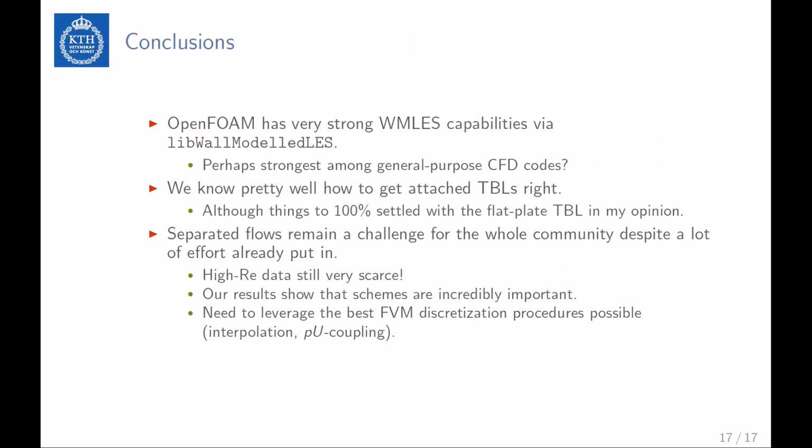So the conclusions are that we have very strong capabilities for wall modeling in OpenFOAM, perhaps the strongest among general purpose CFD codes. We know how to deal with attached boundary layers. For separated flows, the whole community has work to do. We need high Reynolds data because right now it's very scarce. We show that numerics are very important. We have to push and squeeze everything we can out of our finite volume method, and pressure-velocity coupling, all that stuff, because it matters. Thank you very much.